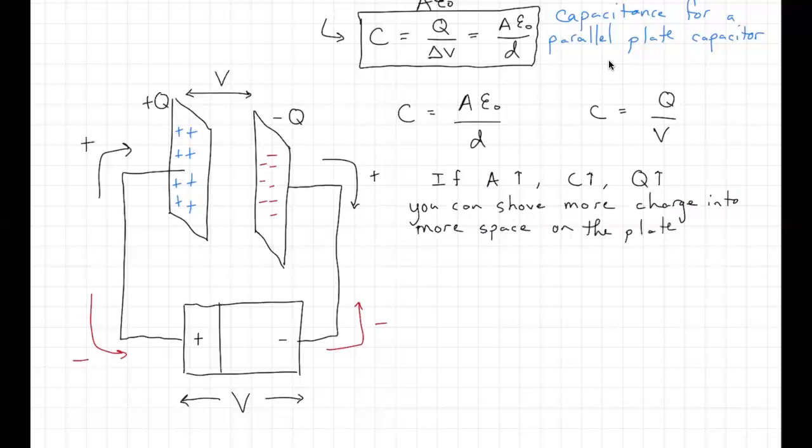So that's one way to change the capacitance. The other way to change it is to change the distance between them. So that distance d that we had in our original setup of the problem. So d is now inversely related to the capacitance. So if d gets smaller, the capacitance goes up. So why would that be? Because if I shrink the distance between these two plates, they're getting closer to each other, and then you get a larger polarization effect from the opposite charges on each plate.